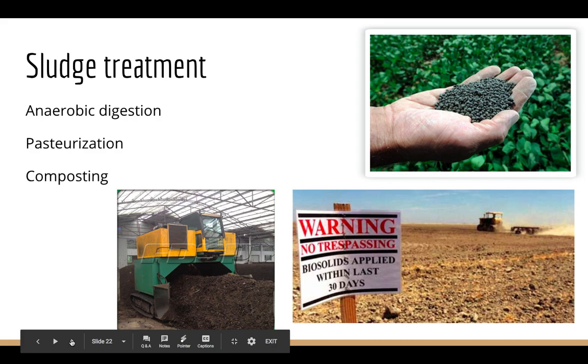At the end of the whole sludge digestion process, what remains is this treated sludge, or biosolids, which is pretty stable, right? It makes a nutrient-rich material when it's suspended in water. The pathogens have been largely eliminated, so you can actually use biosolids for fertilizer. Use this treated raw sludge or treated sludge.